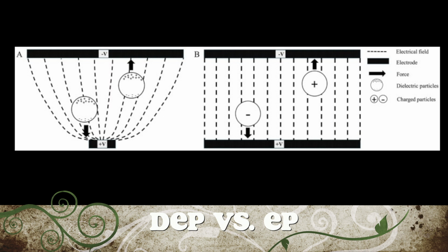So the direction of the dielectrophoresis force is independent of the applied voltage, which means changing the voltage will not interfere with the direction of the resultant dielectrophoresis force. However, the relative polarizabilities of the proteins and the surrounding medium can be manipulated by controlling the frequency of the applied electric field. The DEP force becomes zero at a specific frequency, and the particles do not move. This specific frequency is known as the crossover frequency or zero force frequency.